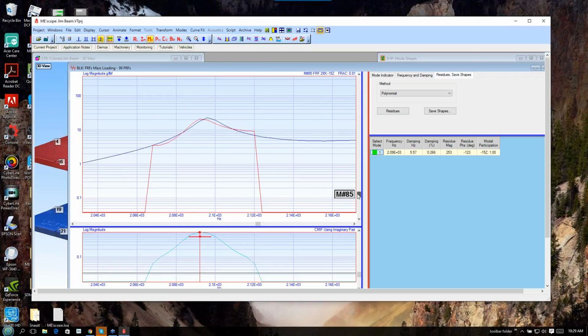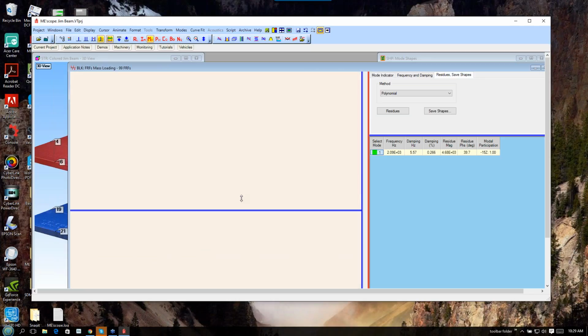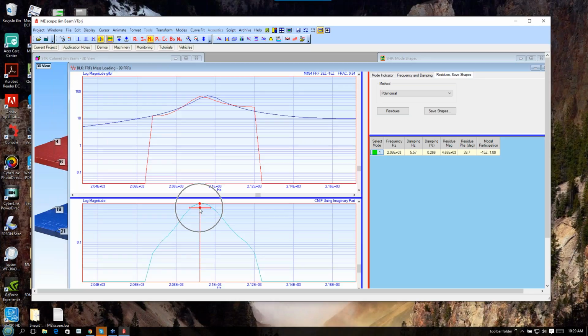because the global fitter found one value of frequency and damping. You can see what it is down in here. If I hold down one of these keys here, I can get the value of that. Well, we've got the value over here, so we don't really need it from the picture. Now I'm going to turn the band cursor back on. Peak cursor or band cursor, it doesn't matter because the fitter is only going to work in that band.